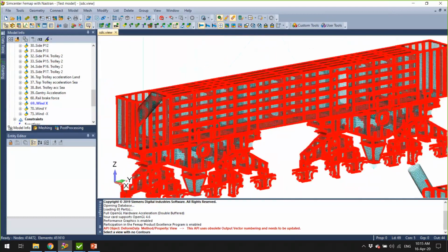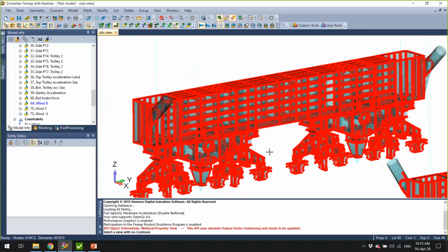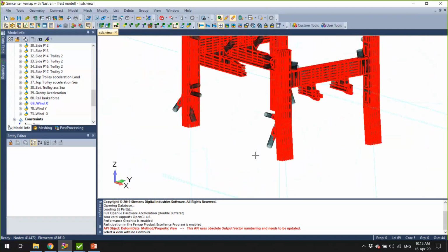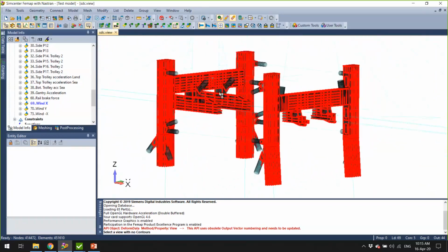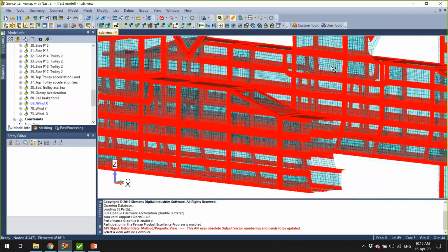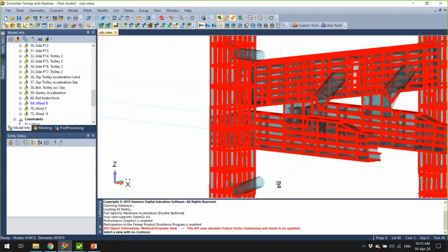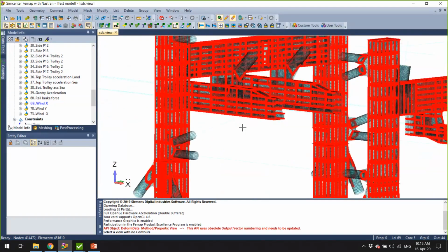It takes it into account as a weld if there is a change in thickness, change in property, change in material, or a perpendicular connection or a connection at a certain angle. So we also have this beautiful node on top, and you can see that all the welds are completely recognized. You need to have a nice mesh and merge nodes, but that's it. After this, the recognition is completely automatic.